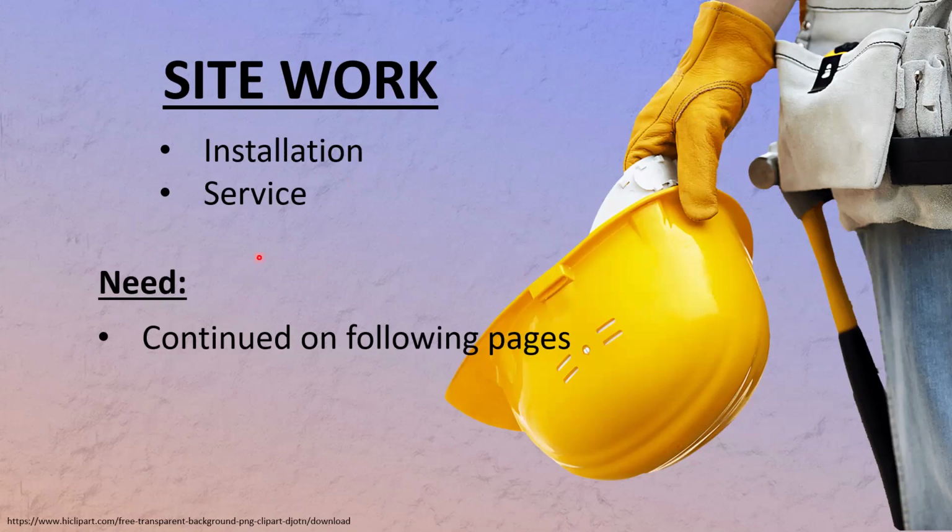I tried to show you as much as I could with the circumstances that we had there. So we terminated some jacks. That's what you'll be doing. Terminated some patch panels. That's what you'll be doing. Even that silly nose prep that looks almost like an insignificant type of lab. Trust me, you will use that a lot. And doing a proper preparation for wire pulling can make or break your day. You will see when you get there. Anything else? All the terminations, all the cable handling and all that stuff. You were going to use that.